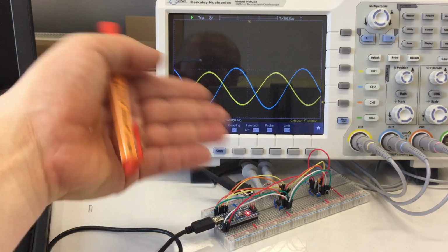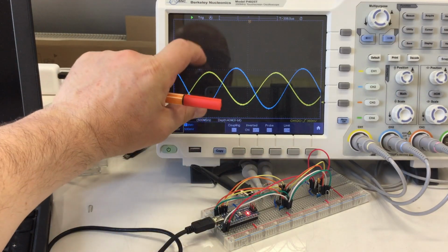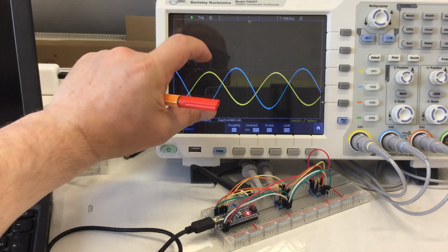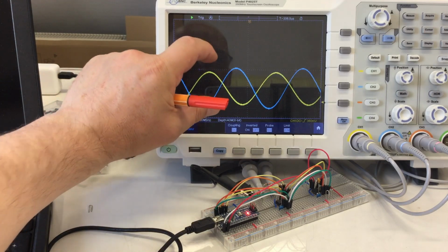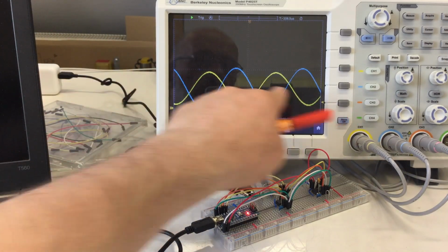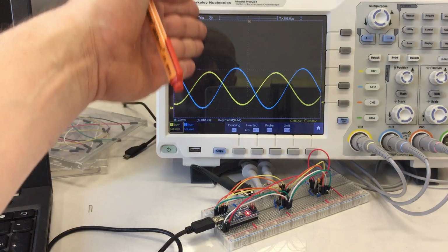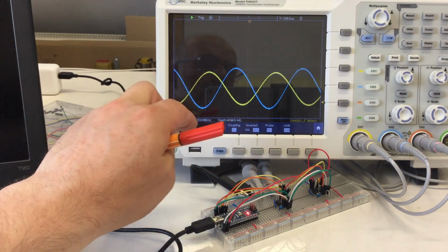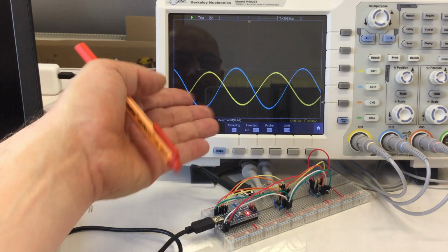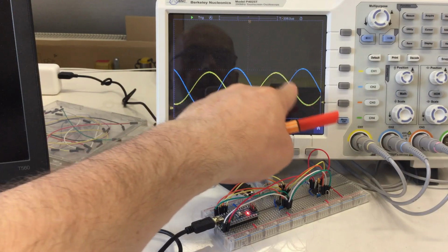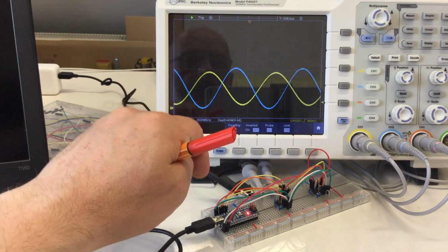This simple method has of course its drawbacks. We already saw the signal attenuation, so if you are relying on specific signal levels, it's not for you. Also the phase shift: if you are relying on a defined phase relationship between the A and the B channel, you can't use it either. However, it makes a pretty nice signal, huh?